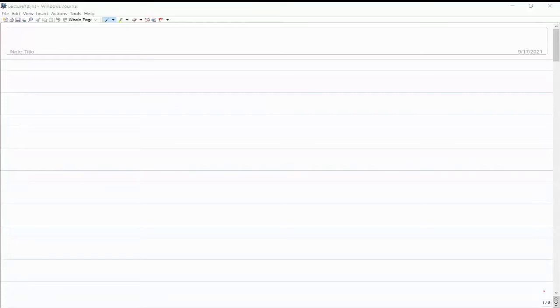If you recall, I had drawn the stress strain graph for the kinematic hardening. Whenever the yield surface is translated, that translation is basically the backstress. That amount of translation is the back stress. And that happens when you are going from tension to compression.